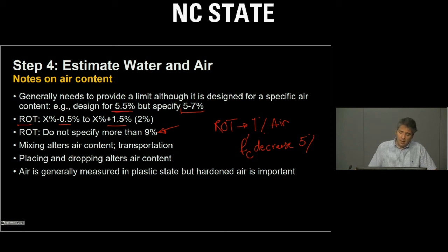Now, you always have to be aware that placing and dropping the concrete will basically alter the air content. The air content that is important is the air content in hardened concrete, but unfortunately, it is measured in the plastic state. Again, you have to be very, very careful about this. Provide the range for this and be a little bit more conservative here. Another thing I would mention is that the mixing also alters the air content.